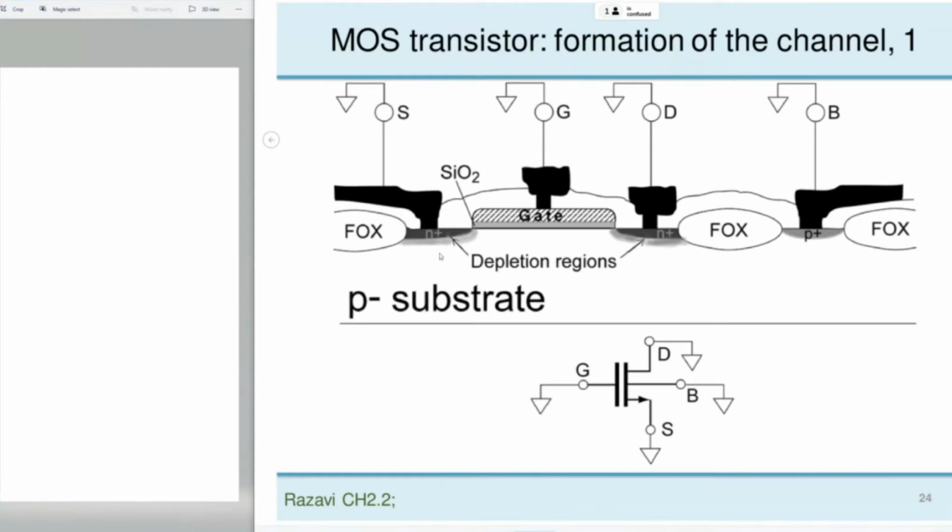Here, these parasitic PN diodes are in thermal equilibrium, of course, so also no current, and there is a certain depletion region in the NP interface. This region extends mainly in the P substrate, because usually the P substrate is weakly doped, and the contacts for the source and the drain are in areas with heavily doped N+ material. So it's a one-sided junction.